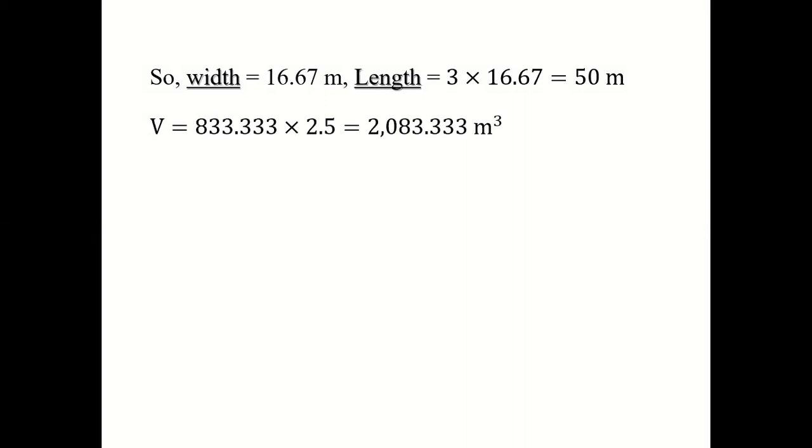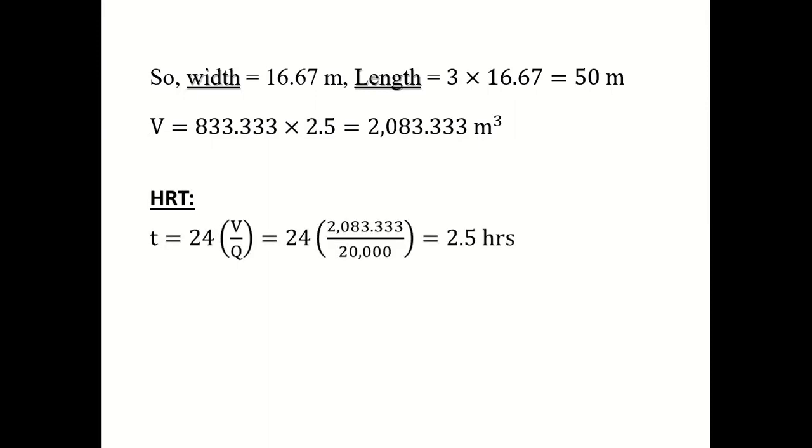And the volume is the area times depth. Area times the depth. So the volume is 2,083.33 meter cubed. Now let's check the HRT, hydraulic retention time. Hydraulic retention time, T equals 24 times V over Q. So hydraulic retention time is 2.5 hours.